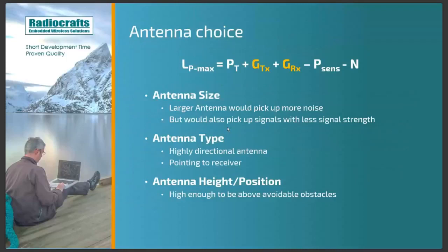In the same matter as antenna choice, we also have the antenna position, which is a more critical thing that you can play with, because the antenna position will also affect the range. And as we discussed earlier, open areas and open fields are the best. So in case you're monitoring something deep inside a big machine, maybe it is good to have an antenna cable and an external antenna for that specific case.